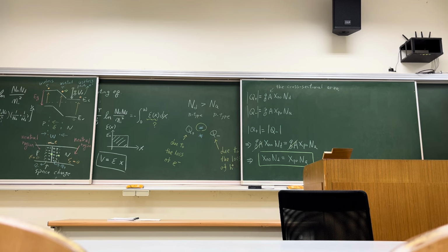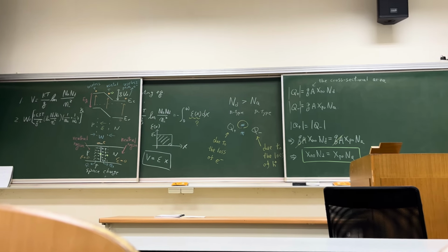If you are considering the power consumption, you want to save as much power as possible, you should increase the doping for the device, because higher doping will give you lower resistance. However, if you want to produce more photocurrents from the sunlight, from the optical energy, you should reduce the doping concentration in order to make the depletion region wider. Right? So there's a trade-off.